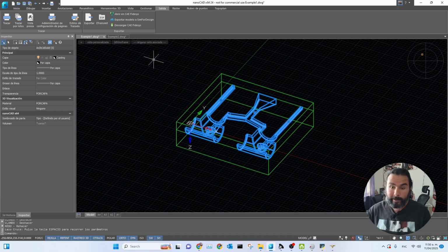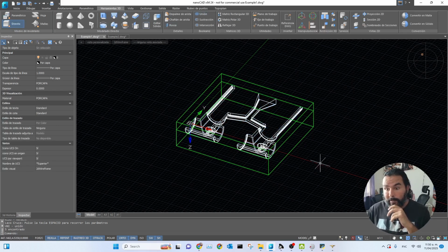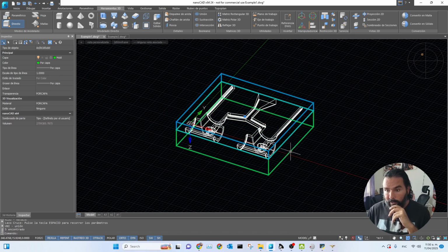Actually, the mesh can be created in parts, but that will generate many more polygons than we need for our work. That's why it's much better to unite them into one. Besides, this simplifies the work of the mesh calculation algorithm itself. We do the same with the mold. We unite the two parts of our mold into a single piece.